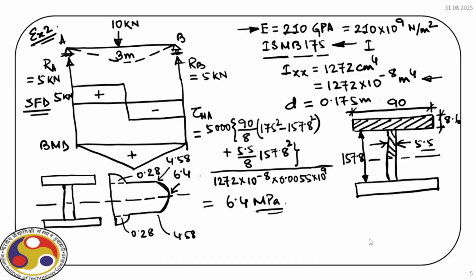Now, before we close today's lecture, I just want to draw your attention that if you look at this shear force and bending moment diagram, so at any say arbitrary section here, you can see the section experiences both bending stress arising from this bending moment as well as shear stress coming from this value of the shear force.